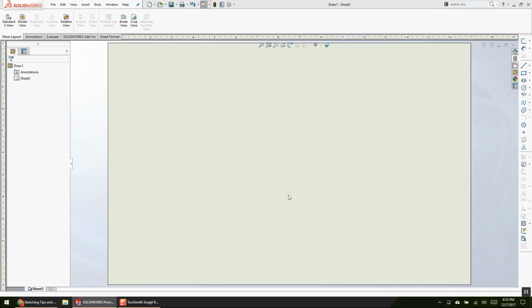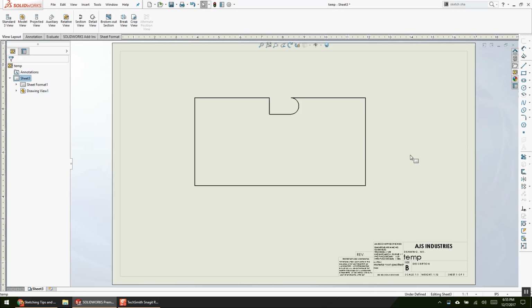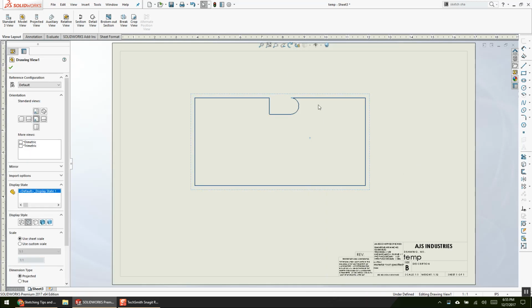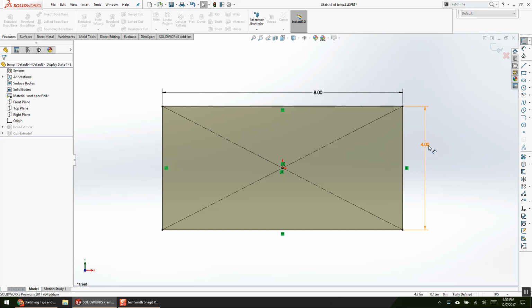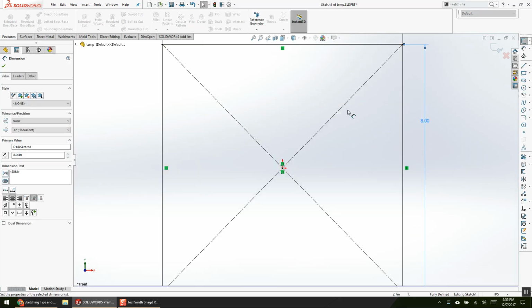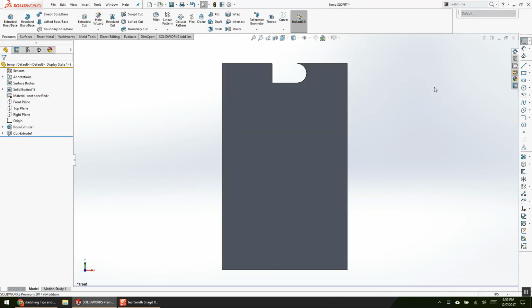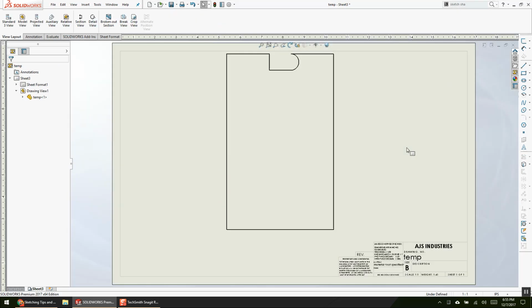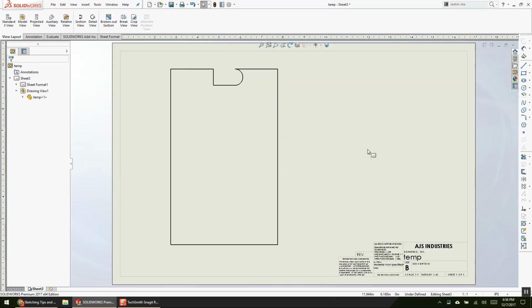Anyway, so let's pretend I'm going to make a drawing for this. I'm attempting to create bad examples like I would do in class. I don't know what this part does. That's a really random part. If I'm going to make a drawing for this, what's the first problem everybody sees? Sharp corners. Yep. Inside. Well, I could in theory do that with a bottom end mill, but let's pretend I really had to have that. We're going to wire burn it or whatever, right? Other than the geometry, to make the base for the drawing that I'm trying to make, what's the problem here?